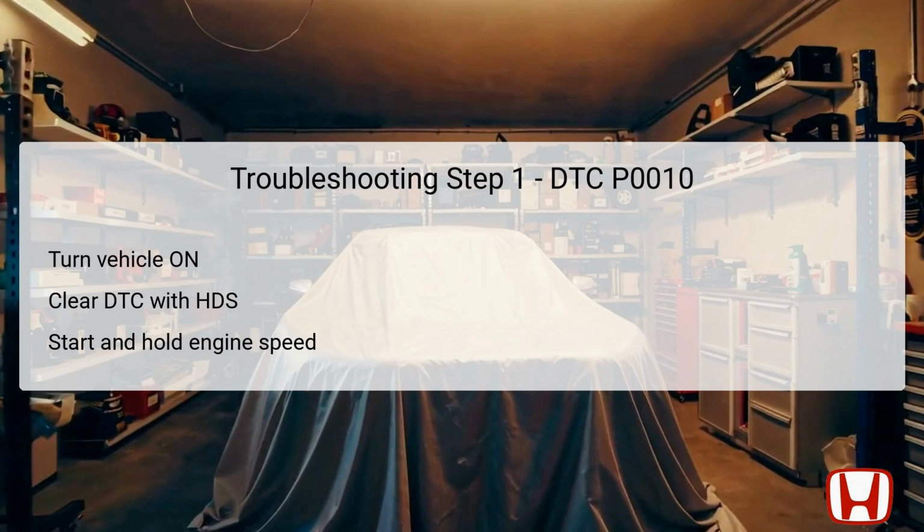Following this, it is essential to clear the stored DTC using the Honda Diagnostic System, HDS, which refreshes the diagnostic data.